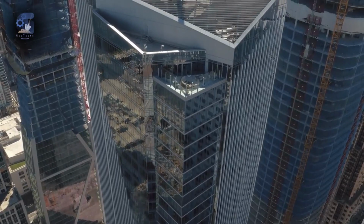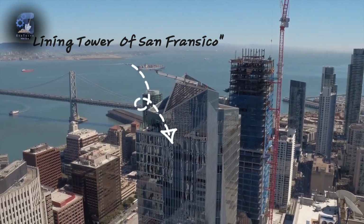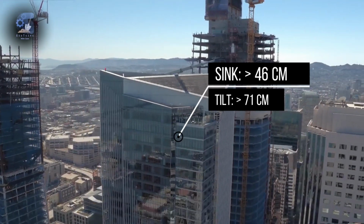A good example to point out is the Millennium Tower in San Francisco, which has gained the nickname the Leaning Tower of San Francisco because the building is experiencing a differential settlement and sinking in a tilted position due to poor foundation design. So, the importance of a properly planned and executed ground investigation cannot be overemphasized.